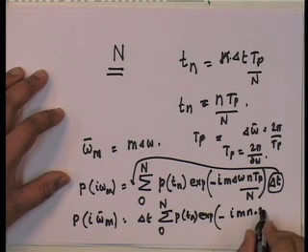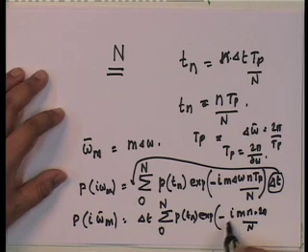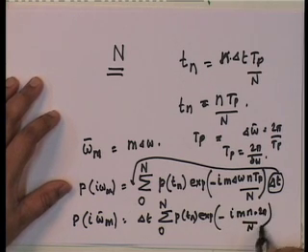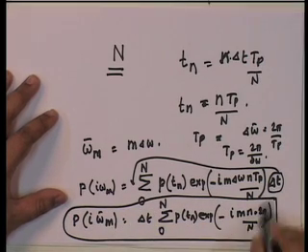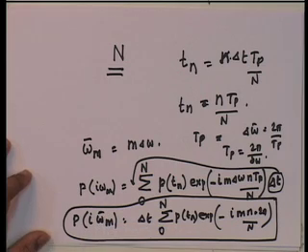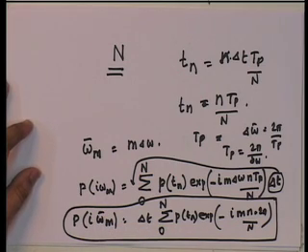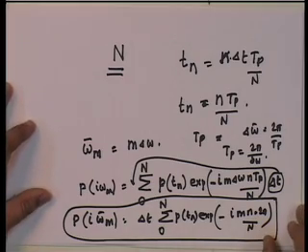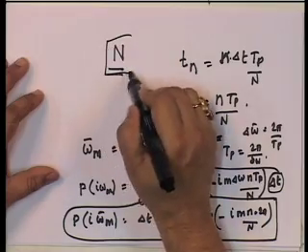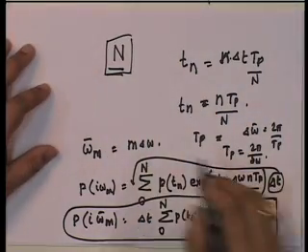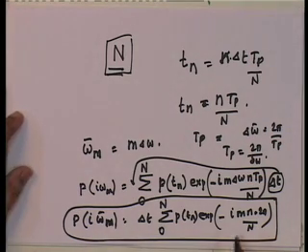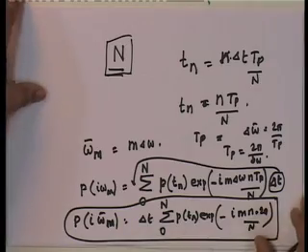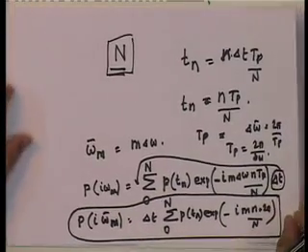So, into 2 pi upon N. So, this becomes i 2 pi m n upon N, and that is my omega term. You see, this is the discrete Fourier transform. Now, therefore, N is defined, and once N is defined, note that how many terms I have will be determined automatically by this.